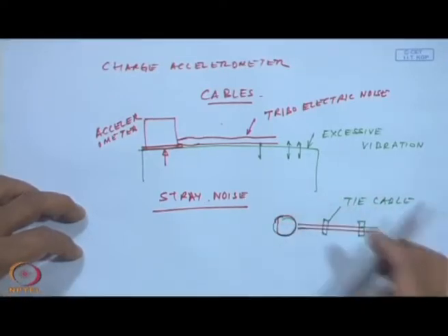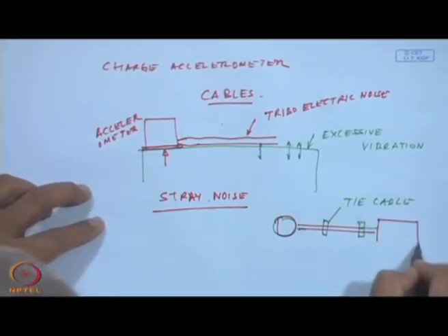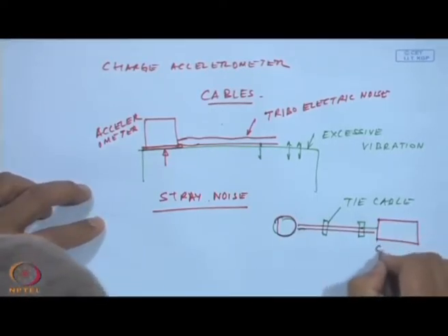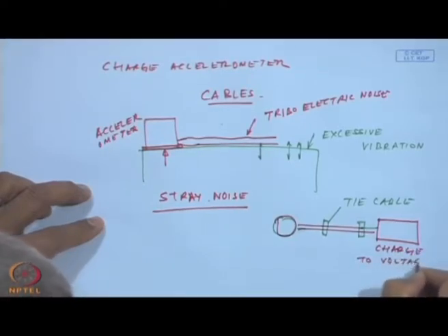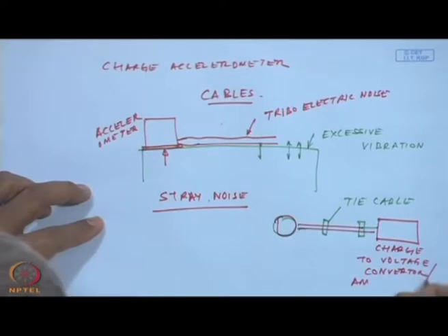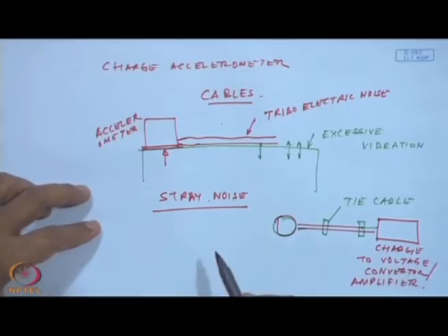And the best way is to have this amplifier, the charge to voltage converter or amplifier, very close to the accelerometer. Okay.